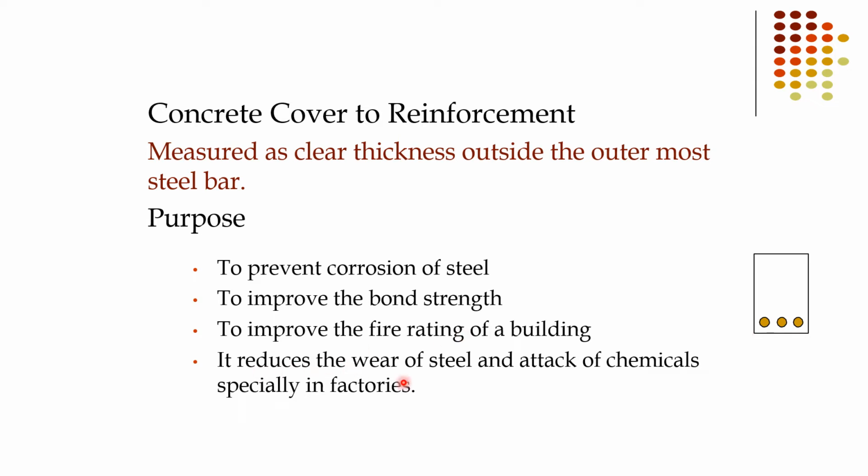It reduces the wear of steel and attack of chemicals, especially in factory areas. If the cover is not present, then the chemicals present in the factories attack the steel bars, our steel bars go under rusting, the main force carrying element weakens in strength, and ultimately failure of the member will occur. So that is very important.